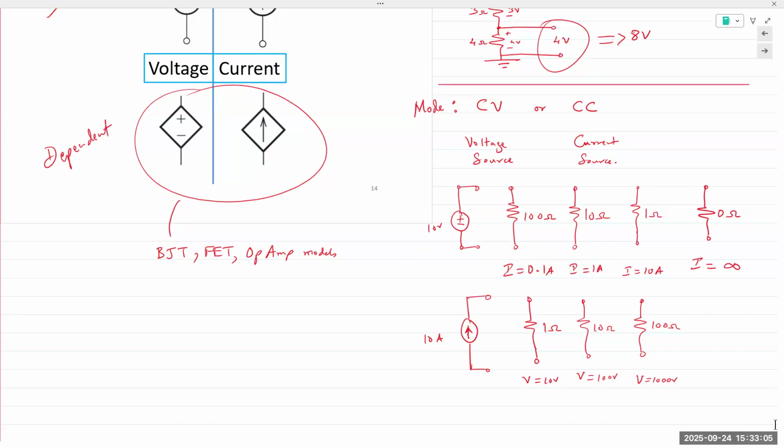A few years ago, we had the exploding phone. Anyone remember that? Samsung Galaxy Note 7. In the pursuit of making the phones thinner, engineers in their battery design made the walls between individual cells very thin. The batteries inside these phones are made up of individual cells, connected in series or in parallel, depending on how they design it. The thin walls resulted in shorting out the positive and the negative terminal. Shorting out the terminal means your resistance is now 0.